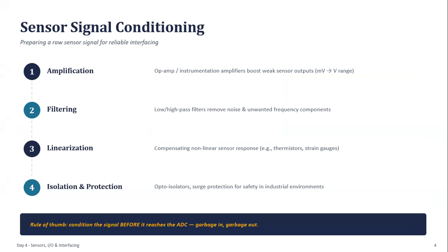Right away, we will move on to the main concept, the sensor signal conditioning system. So what is it exactly? Generally, most sensors generate weak or noisy signals that cannot be directly processed. Signal conditioning improves the quality of the signal before digitization.